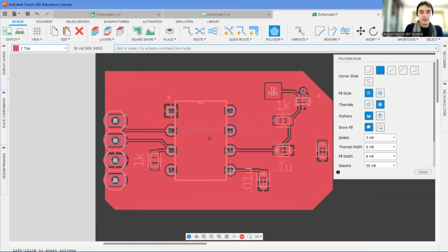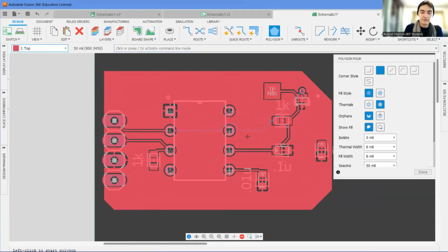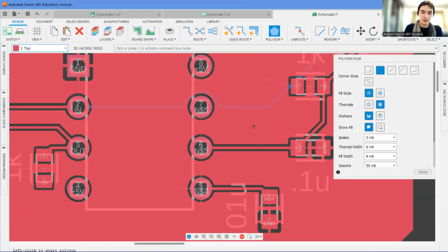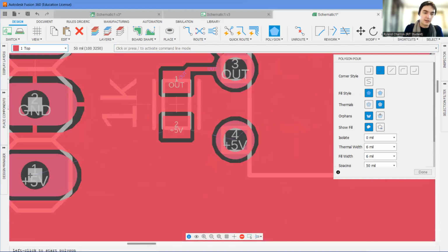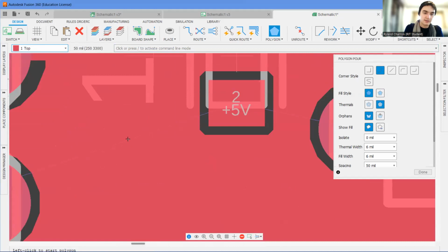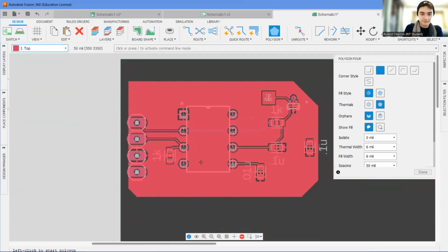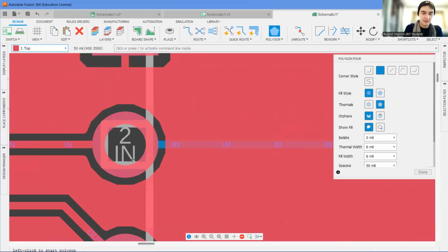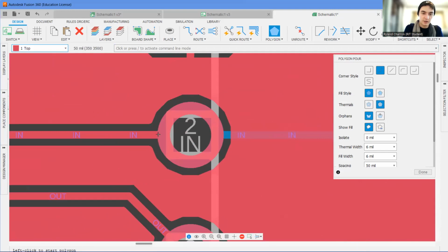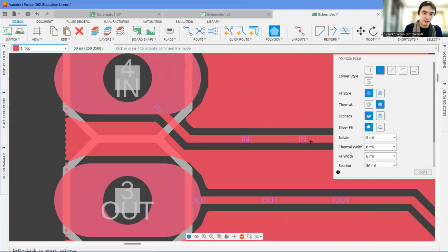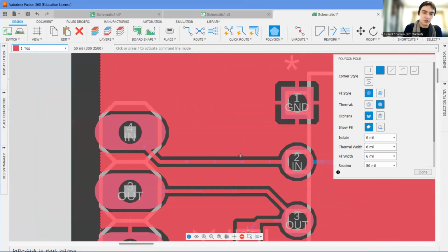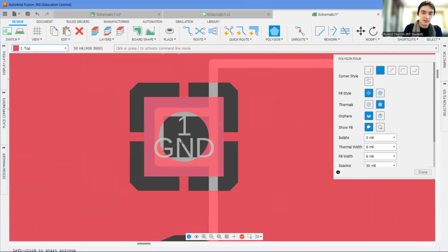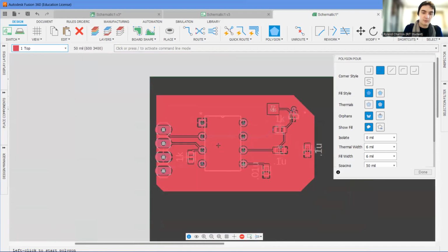So now we added this giant ground signal basically, and all of our ground connections are connected to it. So now the only things that are floating are the 5-volt connections, which you can kind of see through the red. Notice how it automatically accounted for other signals, so it left plenty of space here. If you had a thicker wire here, it would leave more space, but it did connect to our ground pads for what we did want.